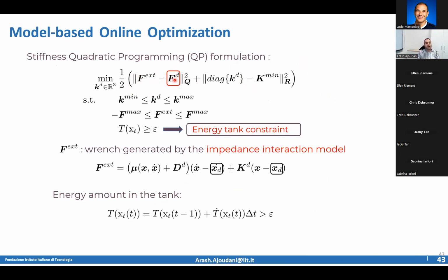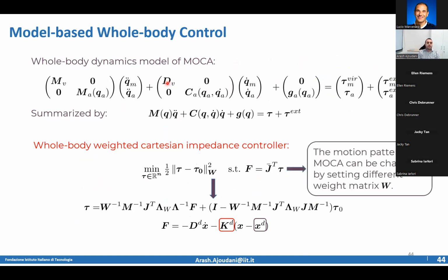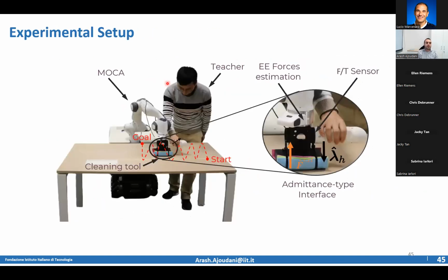This is the desired force that we have learned from the human, but we can achieve this desired force through an impedance controller. So we can actually change the impedance gains, have a really stable and passive behavior, and achieve those really nice interactive behaviors.